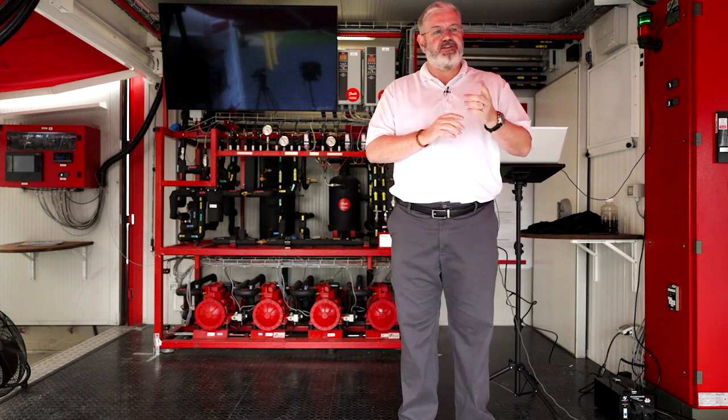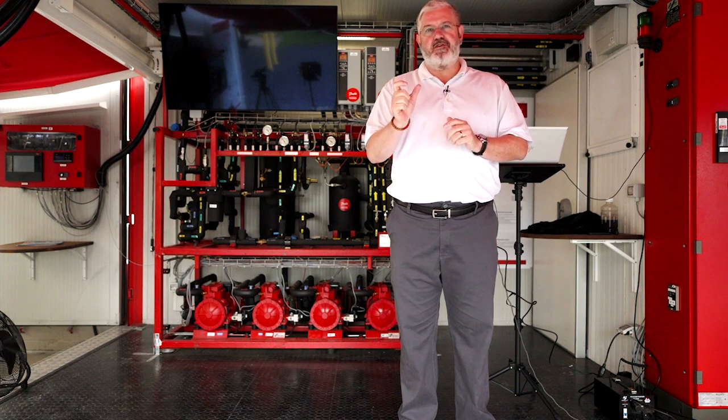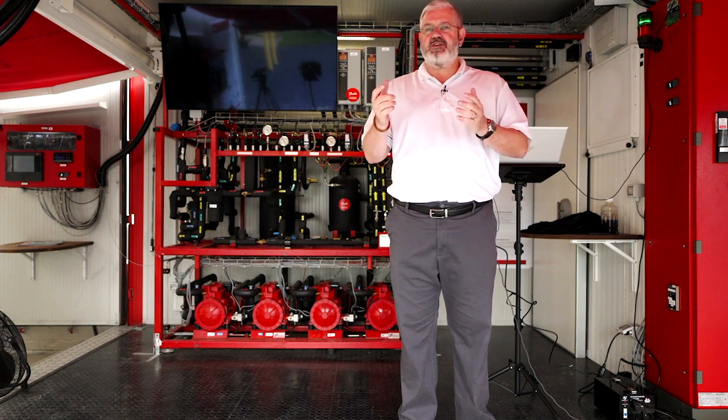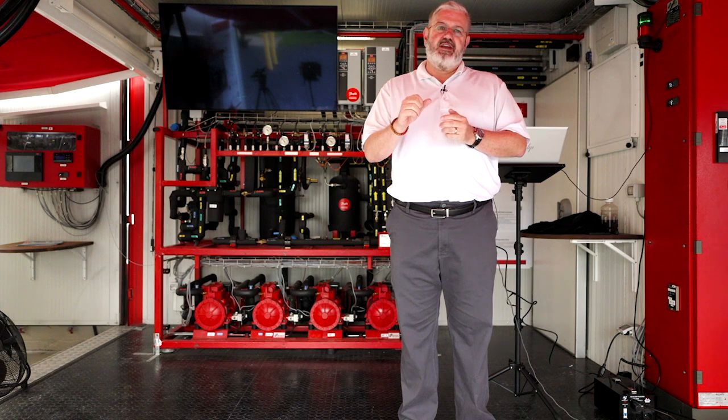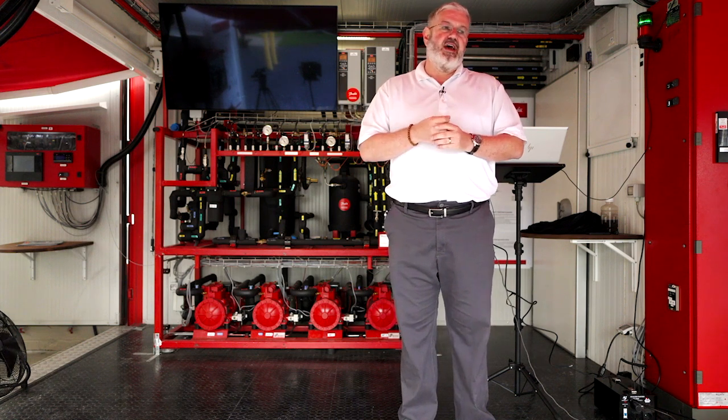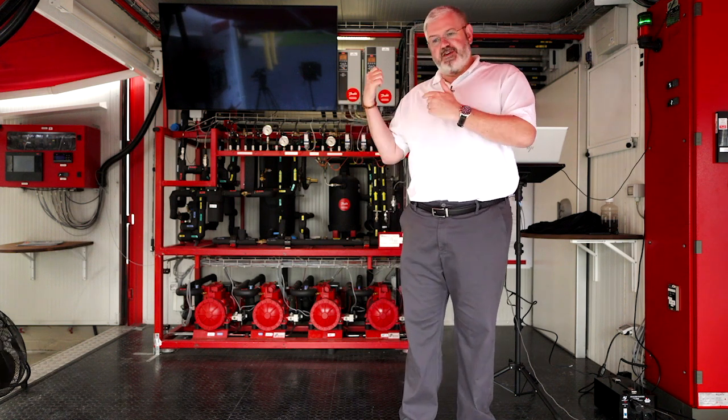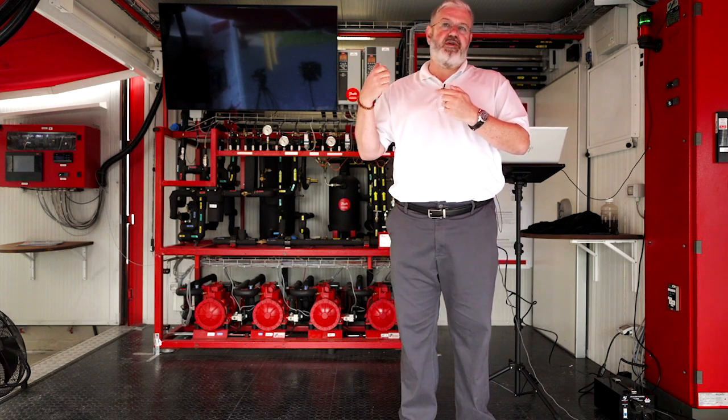But as far as efficiency of the system, CO2 is a much better refrigerant. It just does more work. That's why you have smaller line sizes on the liquid. Doesn't take as much to do the same amount of work. However, there is a trade-off. The components, they're more robust. They cost more to build, so they cost more to buy.